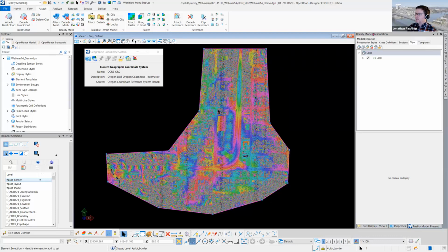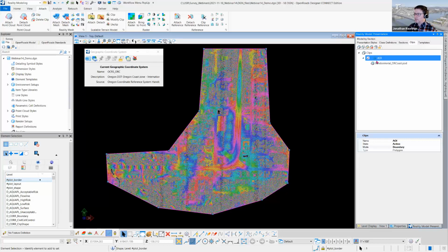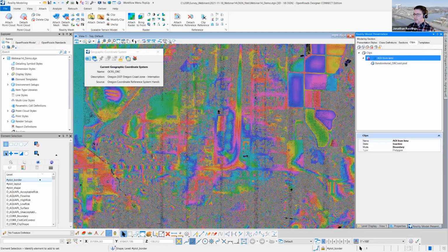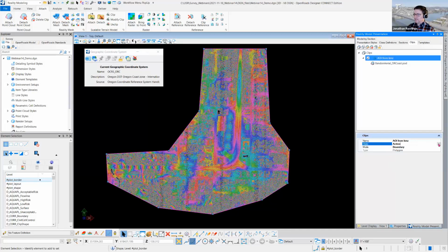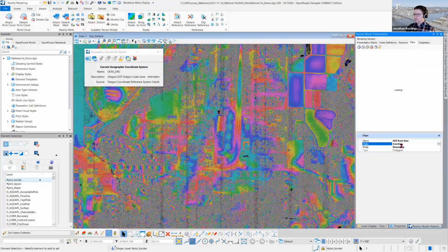Notice under my reality model presentation dialog box, I now have under my clips tab and the clips dropdown, a clip that's called AOI here. I can do lots of things with this. I can rename it if I wanted, maybe. Not totally necessary. It's telling me what pod was used for this clip. If I had multiple pods that were used, it would show them all. I can turn it on and off using the check box. Notice this changed from active to inactive. That's just another way to turn things on and off with the clips. I'm going to leave it on.